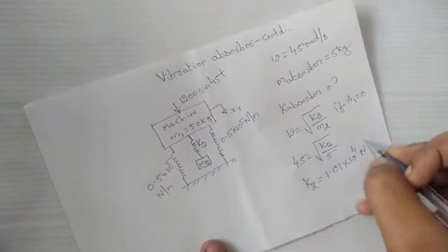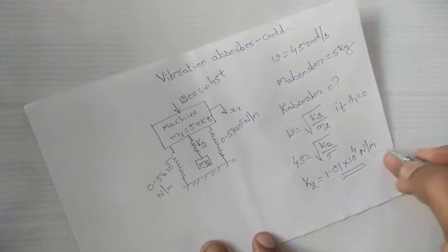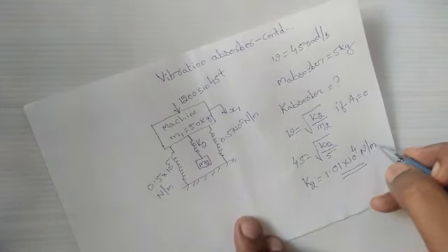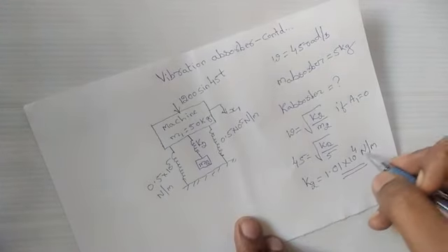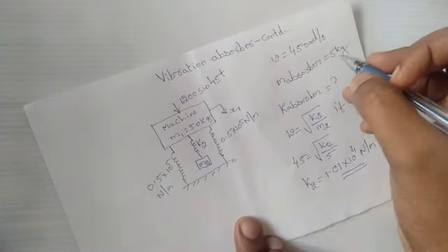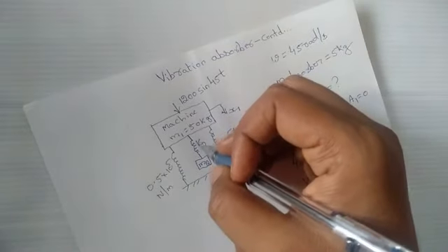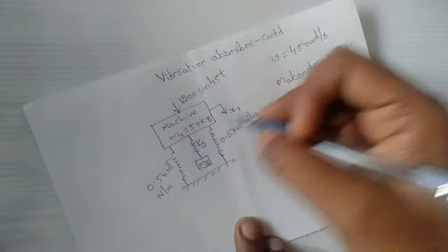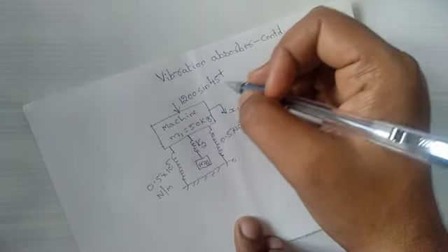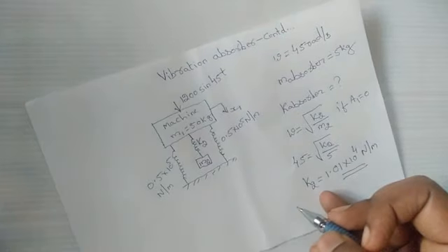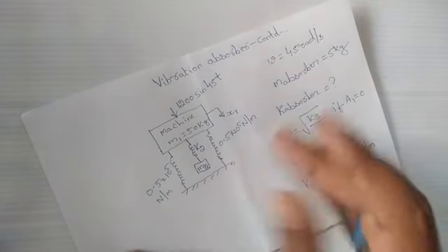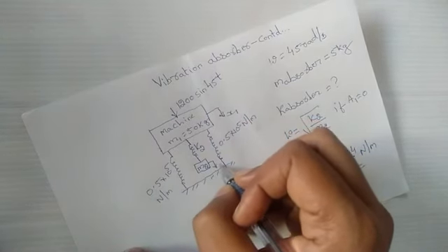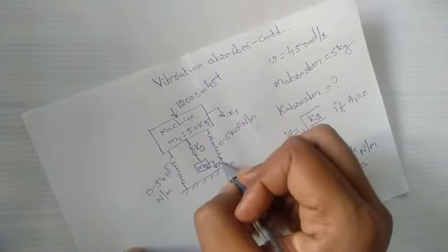If we use this stiffness for the spring of the absorber, and the mass of the absorber is 5 kg, then the vibration would be absorbed by this absorber if the forced frequency is 45 radians per second. So this is actually a 2 degrees of freedom system, because this is x2.